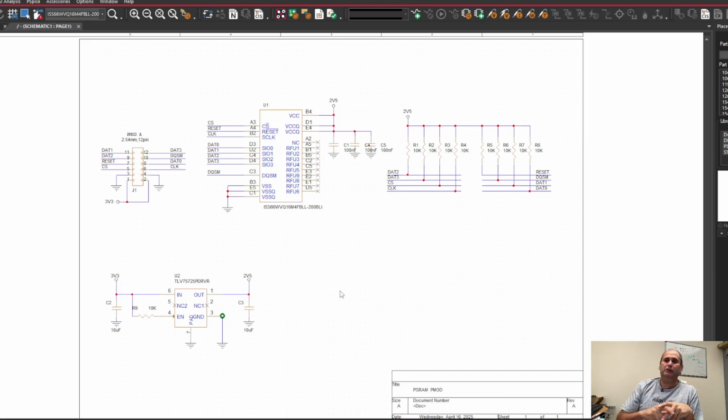I started already the code. I implemented the state machine, and I have the register access, at least the writing access. So I'm expecting that to work, but it's tricky to test because I don't have an oscilloscope which has enough inputs, and I have a logic analyzer which I can use, but it's limited in speed, so I need to slow down everything to a few megahertz so I can sample with it. But I have an interesting technique which I'm about to show you probably in the next video, which you can use in the future, using the board actually to test the IOs.